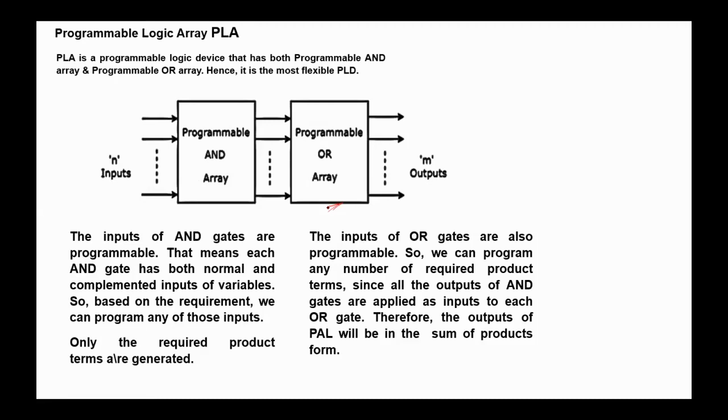The third type of PLDs is programmable logic arrays, PLAs. In PLAs, both the inputs of AND gates and the inputs of OR gates are programmable. So this is the most flexible type of PLDs. Here, only the required product terms are generated.